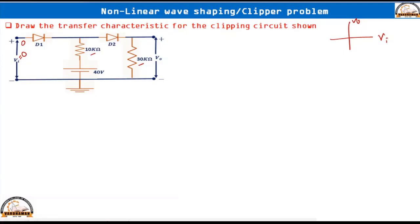If you make the input voltage equal to 0, that is the P side of diode D1 is 0. So if Vi is equal to 0, the P side voltage of diode D1 is 0, but the N side has positive voltage because of this 40 volts.